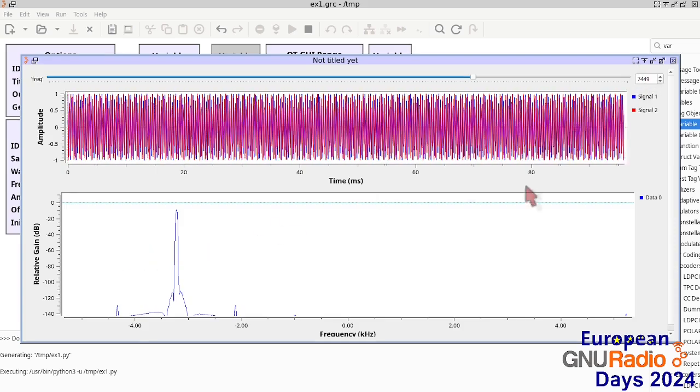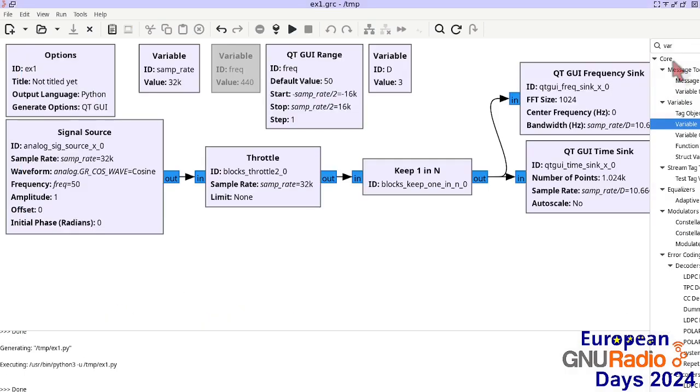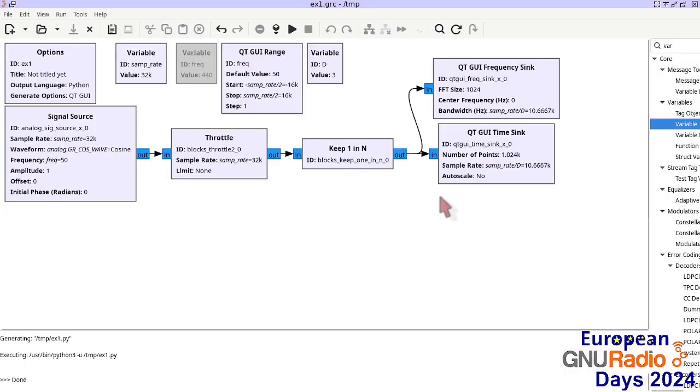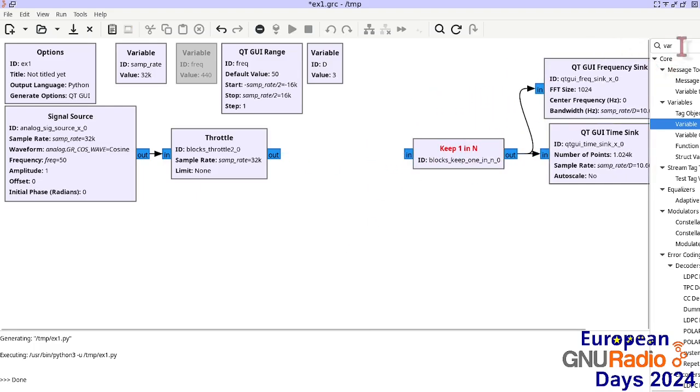So this also tells you that whenever we decimate, we must make sure that we low pass filter to make sure that we do not alias signal back into the baseband. Now in order to low pass filter, we're going to shift a little bit these signal processing blocks over here and insert a low pass filter.